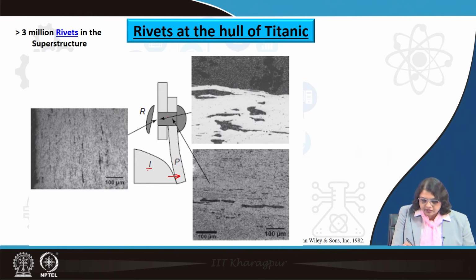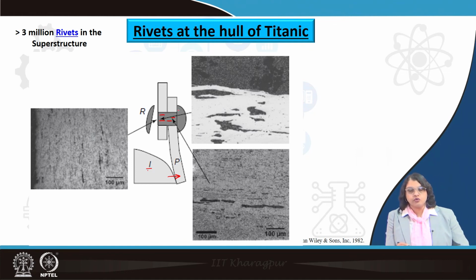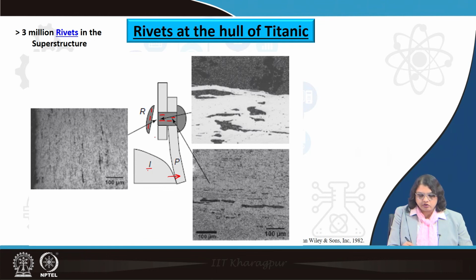Now, you see the stringers which are located parallel to the shaft axis are fine. We know that the stringers which are oriented parallel to the loading direction are fine. The problem is the one which is oriented perpendicular to the loading direction. This was the head that they mounted, and that led to the stringers oriented parallel to the head, but perpendicular to the shaft axis, which means perpendicular to the loading direction, and as a result cracks are easily generated on those, and that leads to popping out of the rivet heads.